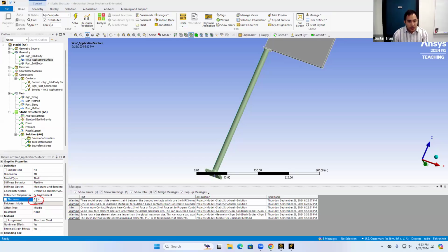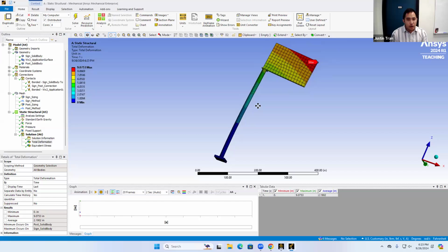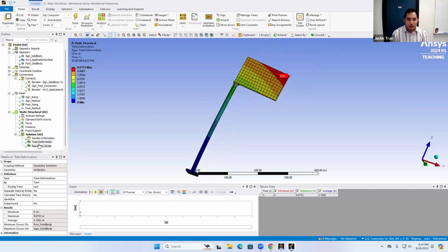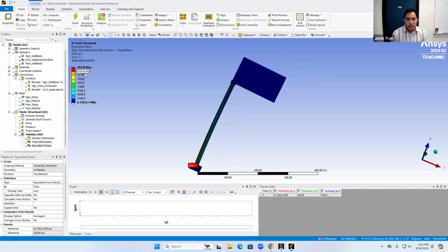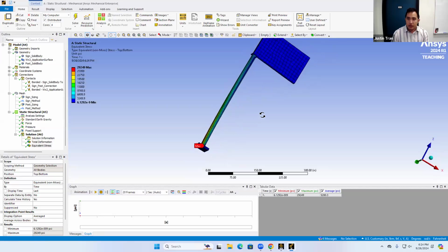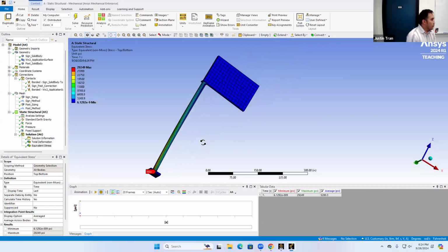If you increase that thickness to 0.1 inches, 0.1 is still small enough so that it's not going to make an impact on the results at all, but it's also not going to completely crumple under the force, right? If you change that amount and then go back to your results, you should get around maybe 9 inches of deformation up top, and a maximum equivalent stress of about 29,000 psi. This makes more sense. All right, was everyone able to get this result here?